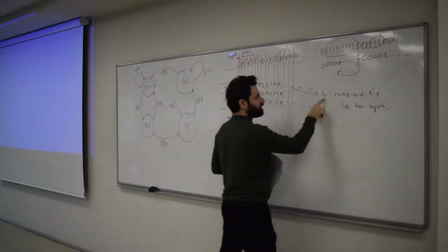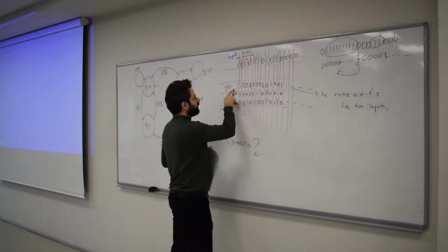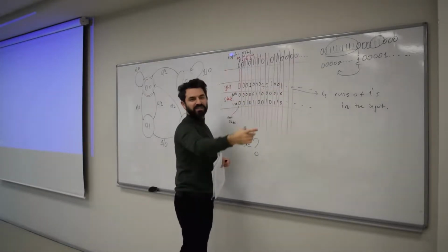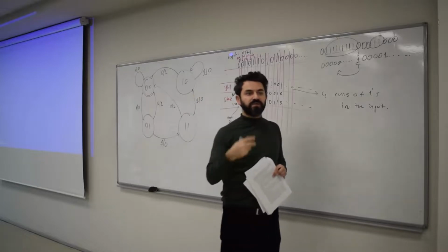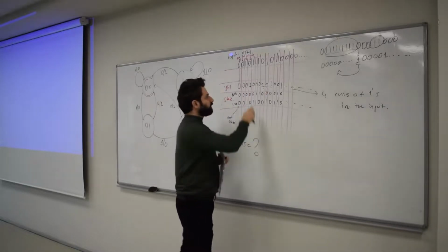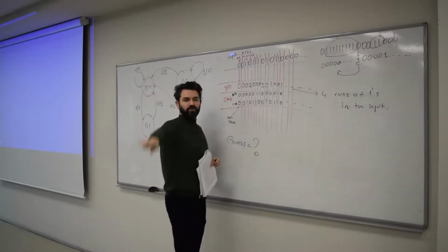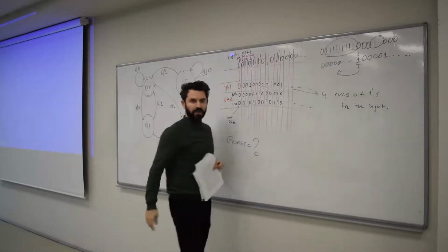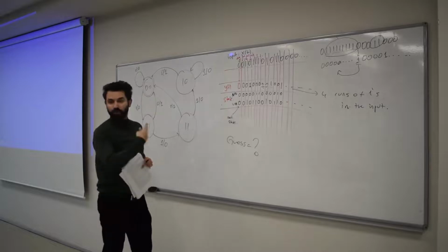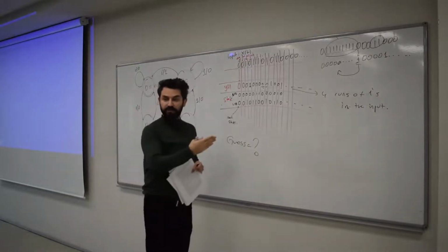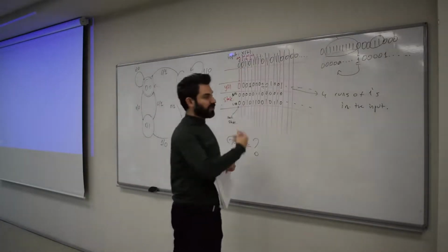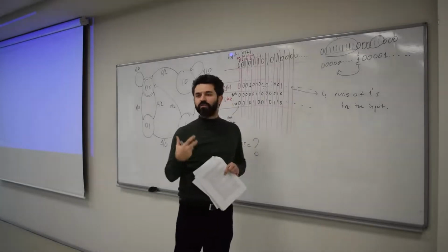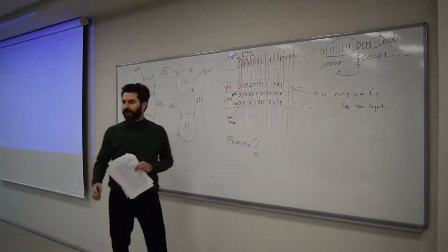Okay, and it's kind of easy to calculate that for a number because you basically push the sequence to a serial adder, which we haven't covered yet, but there are serial adders. It does, long streams of 1s and 0s, it sums them and creates those numbers, okay? So that means this circuit, if this is connected to a serial adder, can actually tell us how many runs of 1s we have in an input sequence, okay?